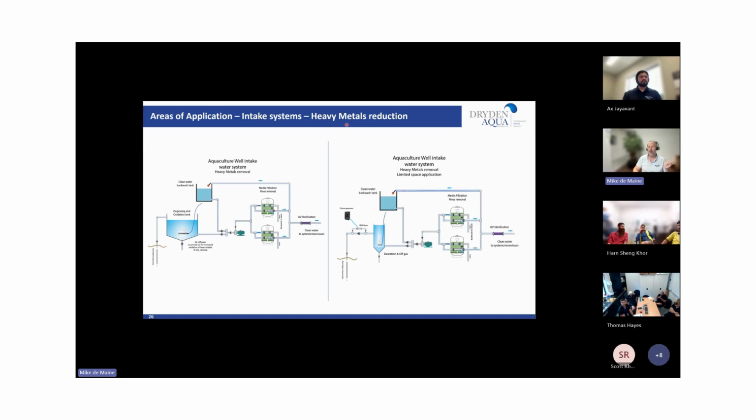So in those situations, I always recommend putting a thin layer of anthracite, not activated carbon, anthracite, on top of the AFM, because what the anthracite then does is it acts as a pre-filtration for the larger particles on top of the AFM, because if those larger particles come down into the AFM, they blind the surface of the media. Any surface can be blinded by large particles, right? So the anthracite removes those larger particles and leaves the AFM to filter the fines.